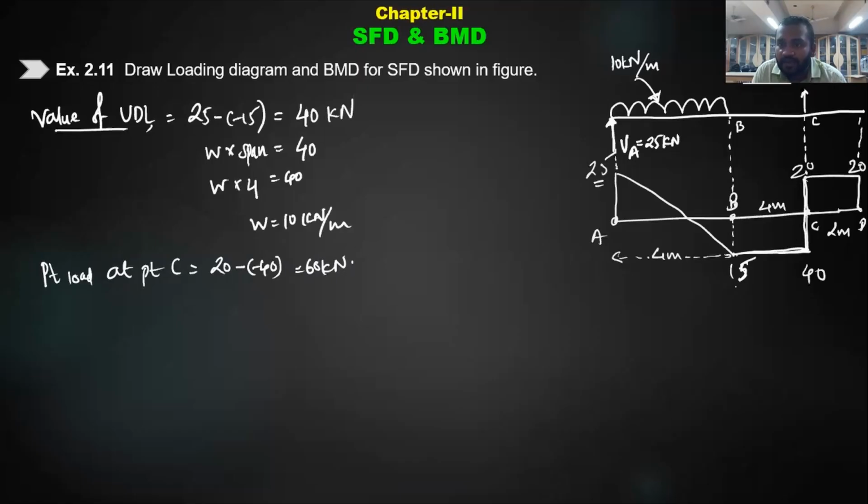So you draw this way and this way, नीचे ड्रॉ करो या ऊपर ड्रॉ करो, that doesn't make any difference, उससे हमें कुछ फर्क नहीं पड़ता, because उसका मीनिंग एक ही होता है. So I will be drawing it as a support, मतलब यहाँ से मुझे पता चलेगा कि ये सिंपली सपोर्टेड तो है, but support B पे नहीं है, C पे. ओके, तो C पे ये लोड कितना आएगा? 60 किलो न्यूटन, and this is vertical reaction, I can call it as at C.